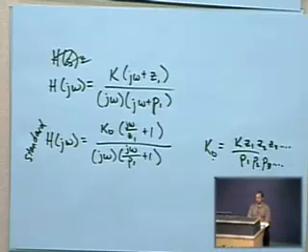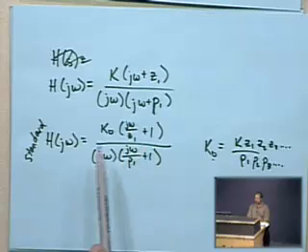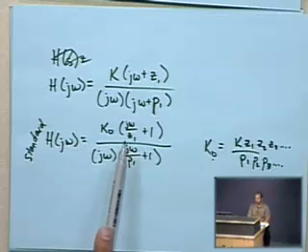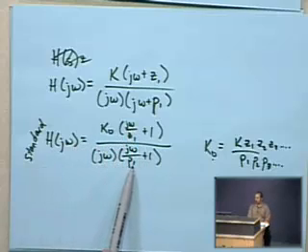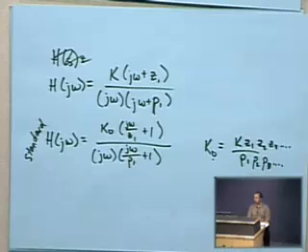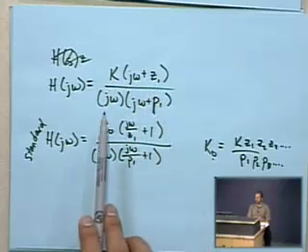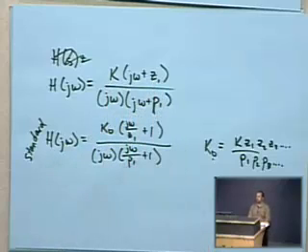Some of the things we've seen in the past, going back to this form of k, involve factoring out the 1 over z1 and the 1 over p1, and that affects how you go from k0 back to the original version of k. But that's the general transformation: you multiply the original constant k times the various zero frequencies and then divide out the various pole frequencies. Good?